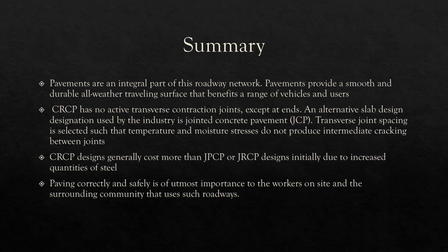In summary, pavements are an integral part of the roadway network. Pavements provide a smooth and durable all-weather traveling surface that benefits a range of vehicles and users. CRCP has no active transverse contraction joints, except at the ends. An alternative slab design designation used by the industry is jointed concrete pavement, or JCP.